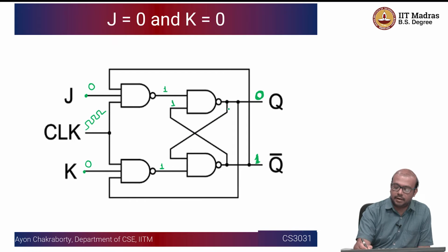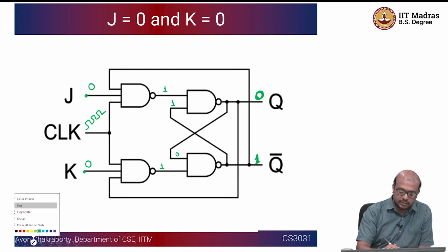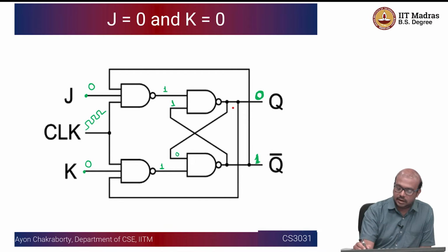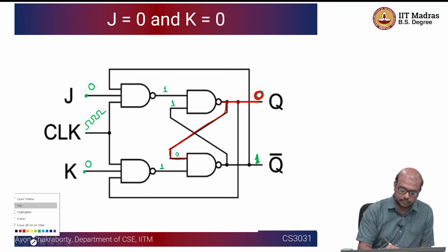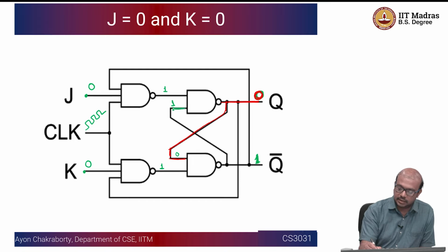Similarly, you have 0 in the same line, and 0 is going to come here. 0 and 1 is 0, but we put a NAND, so this is equal to 1 only. So I'll mark the zeros line with the red color. Let's say this is your 0, this is 0, and the other line is 1.